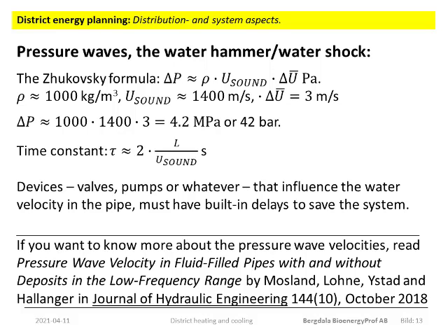Assume that the closing time for the valve is several times longer than the time constant. Then, when the initial pressure shock comes back to the valve, it is still partly open. So the overpressure may escape. And then again, when the second bounce comes back, the valve is still partly open. So first, by the slow closing, the amplitude is reduced, and then the overpressure is allowed to escape successively. So that is why.